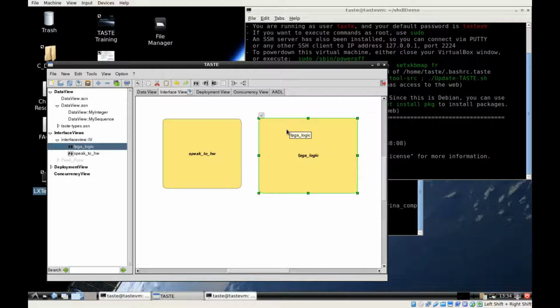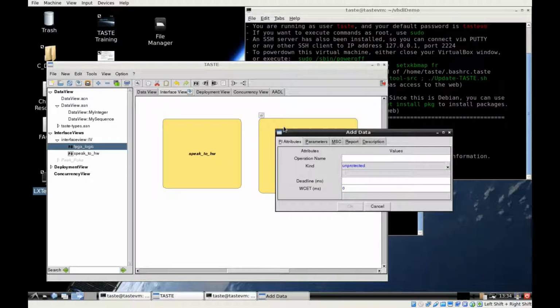So inside the FPGA logic, as we described before, we will have a provided interface. So basically the FPGA logic functional block will provide, hence the P, provided interface, a compute something interface, which will also be a protected one, meaning that it will serialize the callers through a semaphore or a mutual exclusion functionality anyway, that will protect from race conditions. If multiple threads, multiple tasks were calling compute something at the same time, we wouldn't want them to mess each other's results while talking to the hardware.